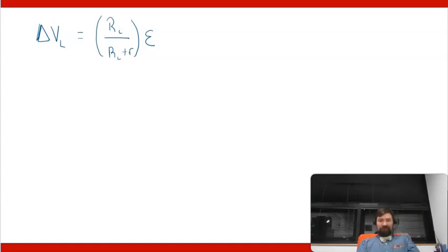So what happens though if we make R L really big? Like maybe the internal resistance is only 1 ohm or 10 ohms or something like that, and the load is 1,000,000 ohms. So I have 1,000,000 divided by 1,000,000 plus 1. That's practically 1. If I have 2,000,000 divided by 2,000,000 plus 1, that's still practically 1.